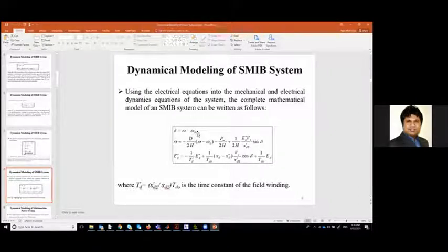This is a third order model. We call it a classical generator model. We can use it straight away in the software, depending on what type of model we are going to use. This is also called a transient level generator model, GENTRA. You will see all this, and I'll show you all the similarities when I talk about the software.